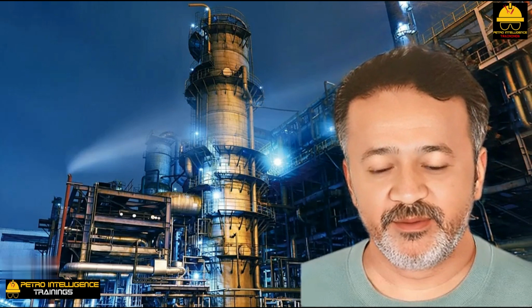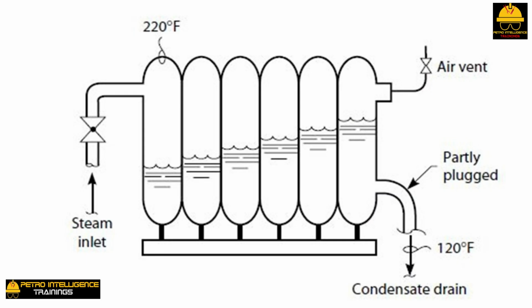It seems these non-condensables are increasing the heat transfer film resistance by interfering with the ability of the steam molecules to come into contact with the cooler heat transfer surface area. A tiny amount of air in a steam condenser will reduce the rate of the steam condensation by an order of magnitude. To restore the efficiency of a radiator suffering from the accumulation of non-condensables inside its condensing coils, the non-condensable gases have to be removed. The air vent shown in the picture serves this purpose.